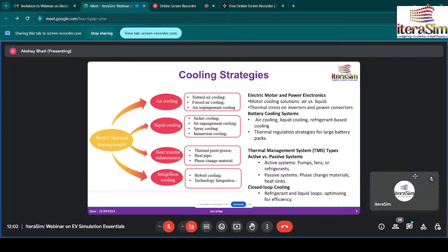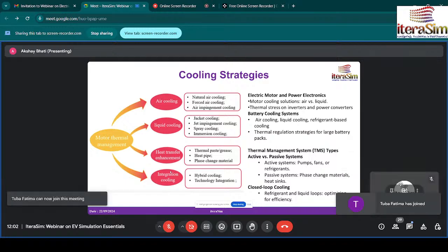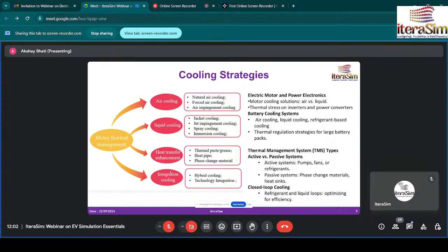It will cover every part of the winding. And another is that it uses the latent heat, because after evaporation of the liquid to vapor, it can dissipate more heat than other applications. And another is that it increases the surface area. The small size of the droplets increases the surface area for heat transfer, enhancing the cooling efficiency. And spray cooling is used everywhere in cooling electronic components where high heat flux is generated. Very high heat flux means higher heat is generated in a lesser area. That is why it is named high heat flux.